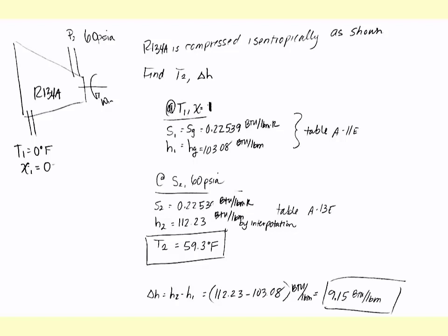How do we use that to find whatever else we want? And what table are we on? Okay, so let's go to the pressure table at 60 psia. So at 60 psia, what is S sub G? Yeah, bring your book. Okay, so at 60 psia, on the saturated liquid vapor tables, what is S sub G?